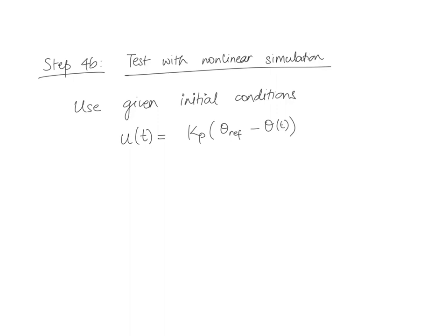It's just 0, but this is the most generic form, plus Kd multiplied by theta dot reference minus theta dot. Both of these are 0. So all you have is Kp multiplied by negative theta and Kd multiplied by negative theta dot. Desired minus actual. So this is just equal to minus Kp theta minus Kd theta dot.